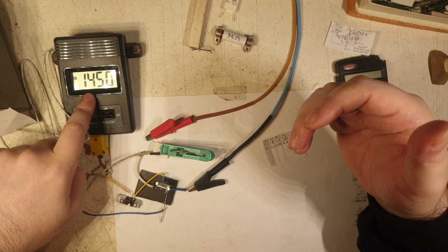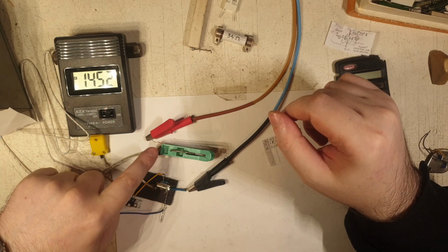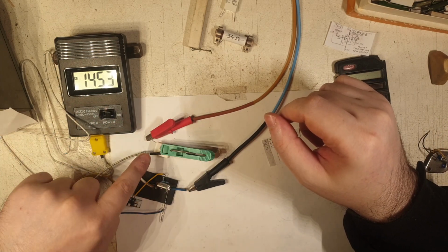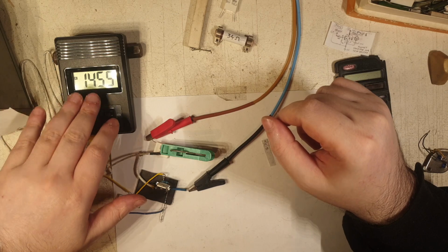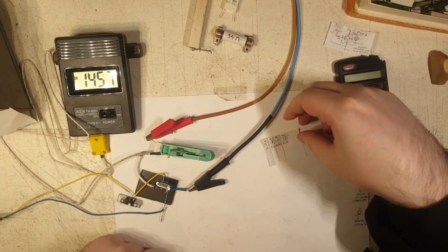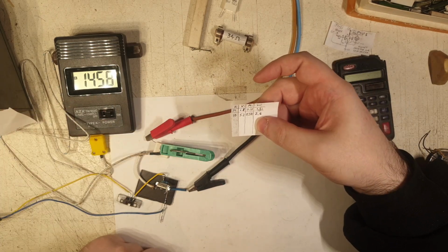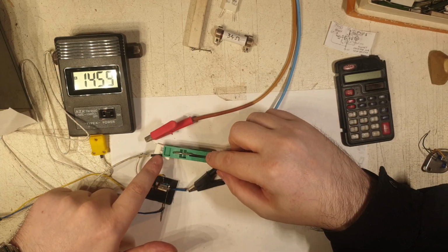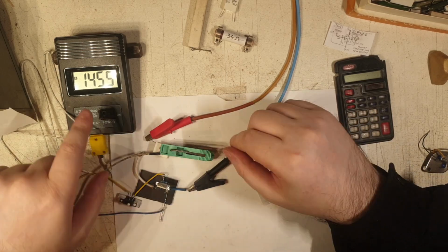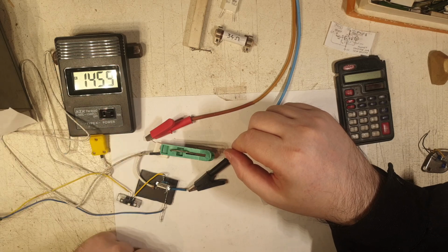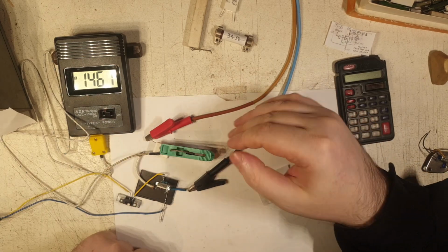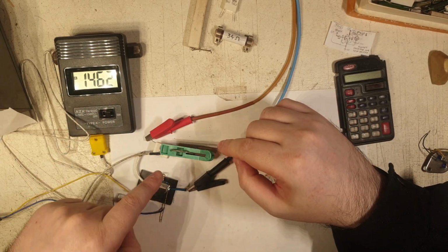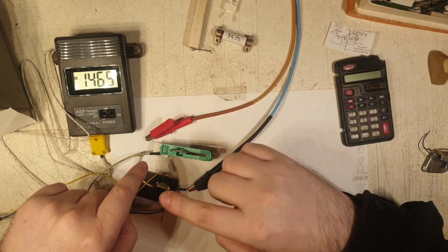Unfortunately, I don't like this temperature that I'm getting over the resistor, but I really don't care that much if the resistors get to this temperature. Usually they shouldn't get to this very high temperature, especially at 2.5 watts, which is exactly half of the rating of this resistor. This resistor is rated at exactly 5 watts. So doubling this means 300 degrees Celsius when it's conducting 5 watts, or even more, because this will derate substantially.